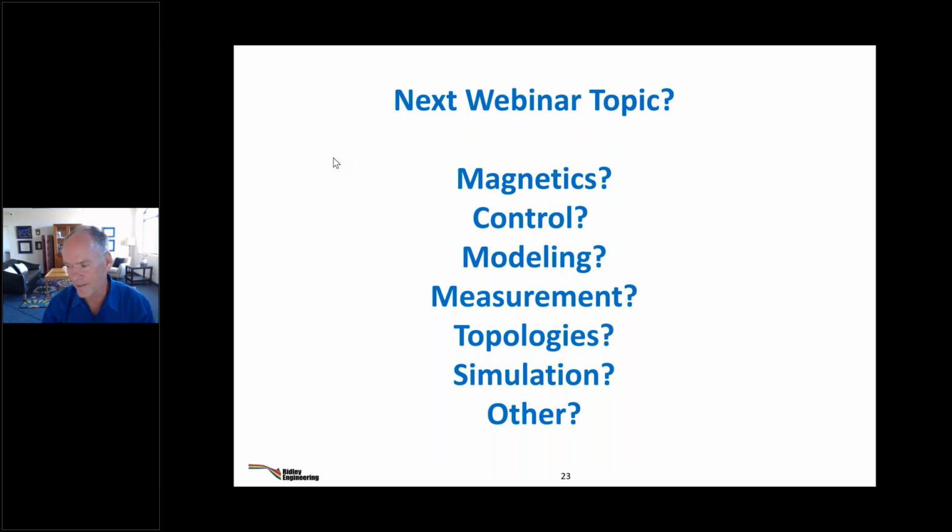So current sharing can be a little difficult between them. Getting into digital control at that point, really. Is it challenging to parallel the LLC? Yes, it is. Is it done? Yes, it is. So everything's a challenge. LLC is a challenge, absolutely.